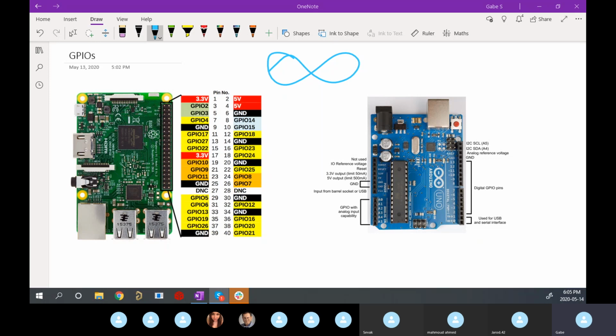We have a microcontroller, you have a microprocessor, you have a system on a chip, and they're all basically different tools for different times, right? You want to use a microcontroller when you have a very fast, lightweight system where you have a very specific task. A microprocessor is more powerful and more general. That's where you're going to run an operating system like Windows, and you're going to have software developers develop applications like Chrome and Altium and OneNote on top of that.